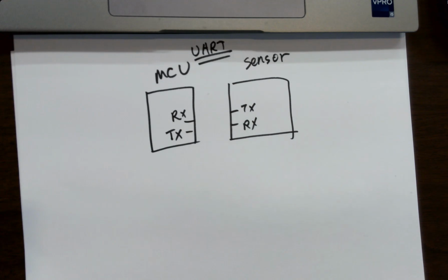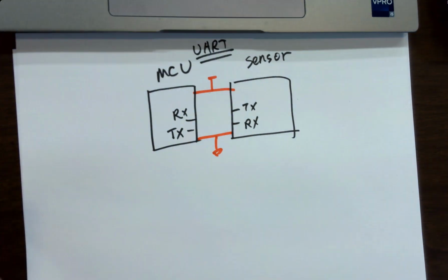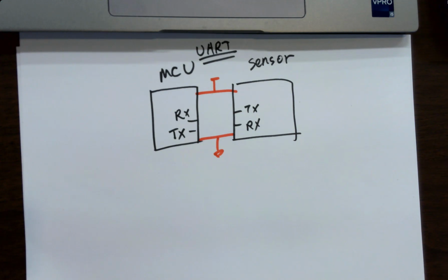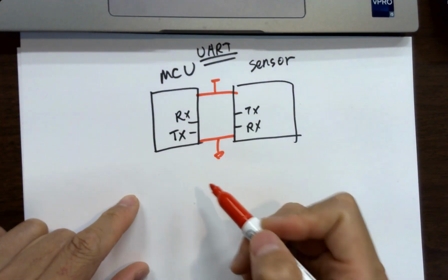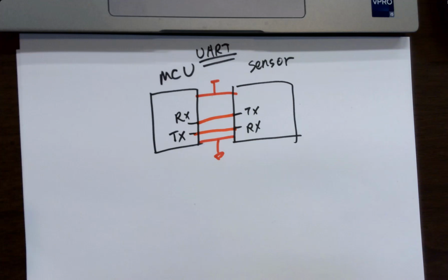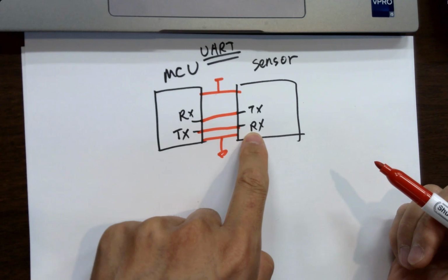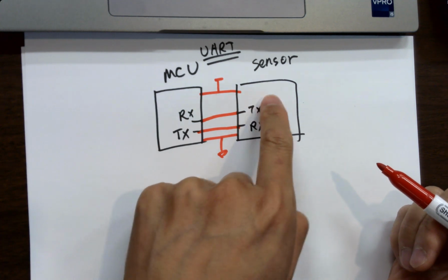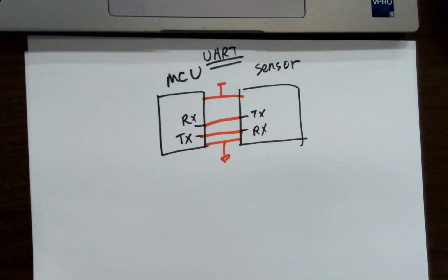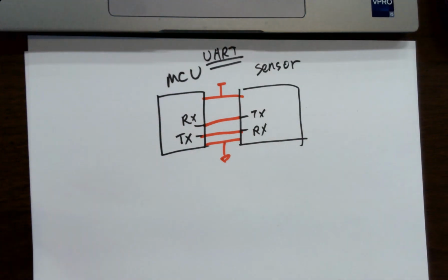You just simply connect two ports actually. But definitely there's power as well, right? And ground. If you're counting power and ground, there are totally two lines. It's communicating with a certain digital protocol. So you connect RX to TX, TX to RX. That makes perfect sense because this one is receiving from the transmission here, right? And the other one is receiving from the transmission of the other one. So TX to RX, RX to TX. Just two ports. However, where the TX and RX of the laptop are is unclear because it's already converted.